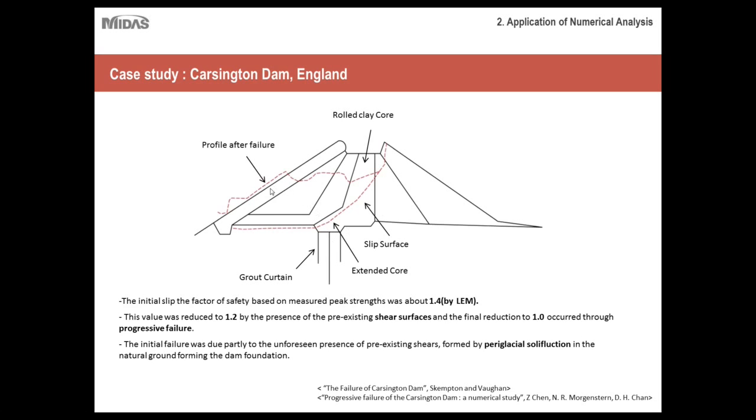If you can imagine the water level was around here for this dam, just imagine the water being frozen at one point. As we all know, when water freezes, it expands. So when the water in the soil expanded, it caused additional shear. And then ultimately it melted, causing additional shear. This happened over the course of, I believe, several months. So over time, the shear stress became too much for the slope, and it led to its failure.